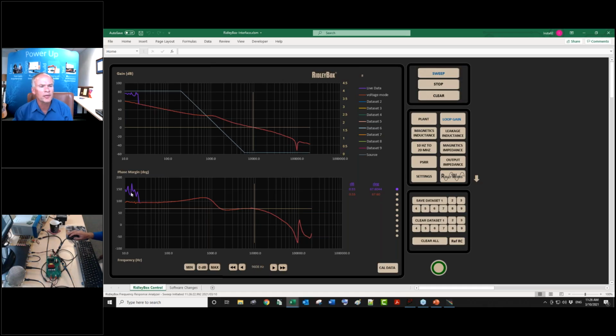You see the gain cleaning up, the phase is cleaning up here, but now you're getting to the resolution of what the AP can do. It'll go 90, 100 dB, no problem. The other analyzers, which are not our AP, don't have quite as much resolution. But hey, look, I got lots of gain here. Do you really care if it's 80 or 90? Not so much. So now we've gone current mode, and we're comparing a current mode loop with a voltage mode loop.